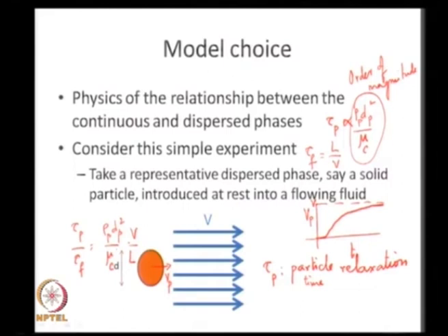If this dimensionless number is much less than 1, I am ready to use the mixture model. Okay, mixture model as one possibility. If this dimensionless number is much greater than 1, I have to go to the two phase model.